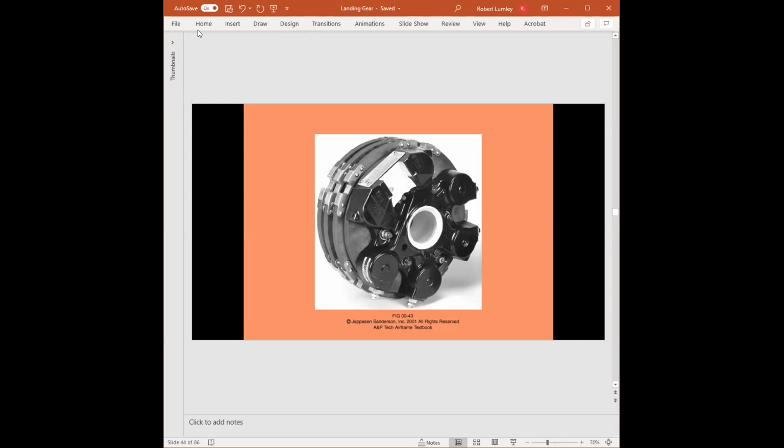So get rid of them. But they knew they had something. And so the engineers went back and they redeveloped the carbon matrix of what the material is made out of, or the formula, if you will. And so today, a lot of aircraft are now coming out with the carbon brakes. They can handle a lot more heat than the standard style brakes. They're lasting longer, they weigh less, but they cost a lot more than the initial. But the payoff is over the long run, you will save money.